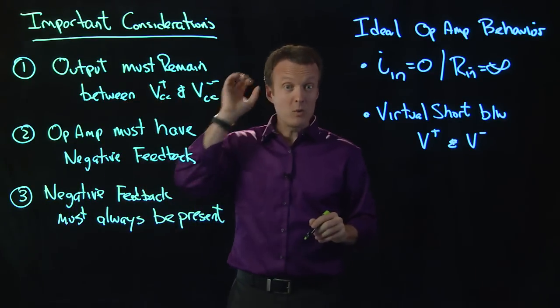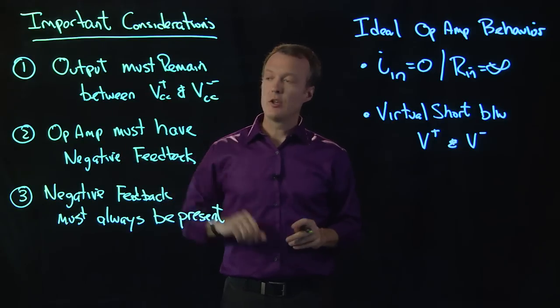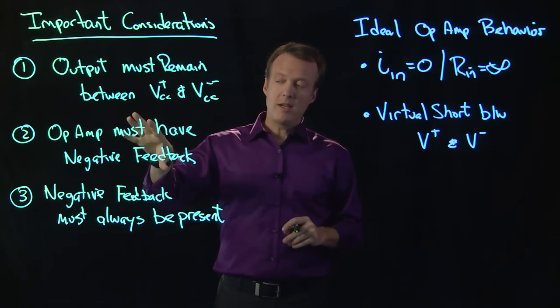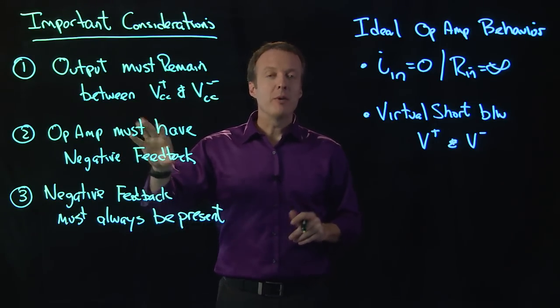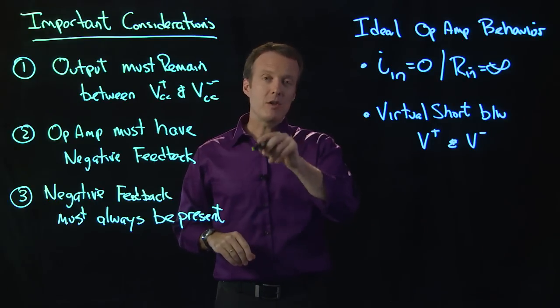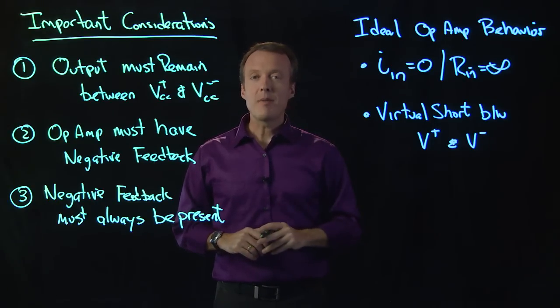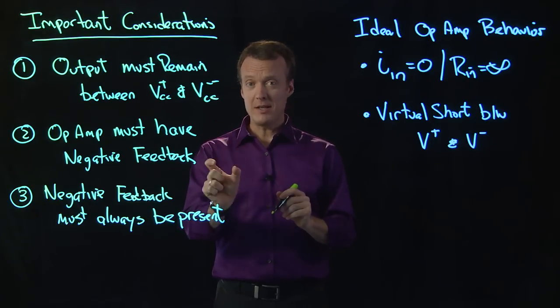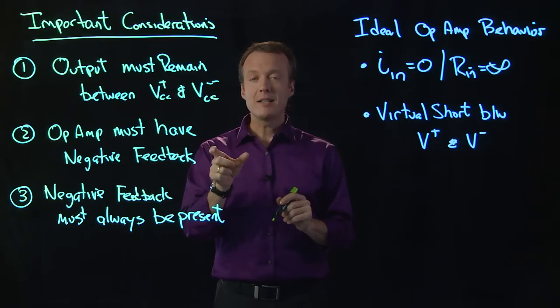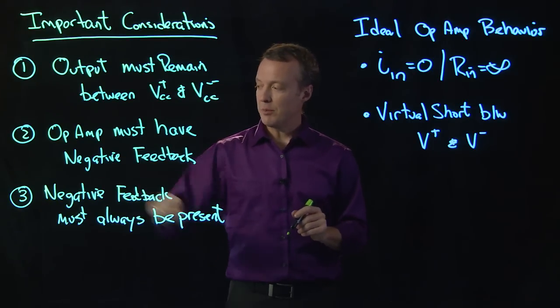So that's one of the reasons why the integrating circuit that you learned about previously was described as a circuit that's not really practical, but that you must turn it into a leaky integrator so that you have a high resistance in the feedback path, because the capacitor in the feedback path at DC would act as an open circuit and would violate this third principle.